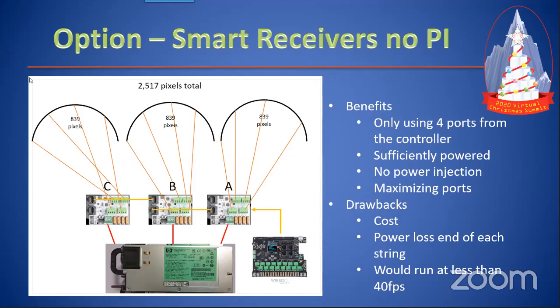In this particular manner right here, the four ports are shared across the A, B, and C. So we'll just call it port 1. Port 1 here is driving 200 pixels. Port 1 here is also driving 200 pixels. And again, port 1 here is driving 200 pixels. So out of that specific port, you're actually utilizing 600 pixels off the board, just in a dispersed manner.